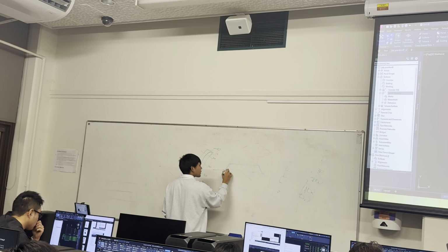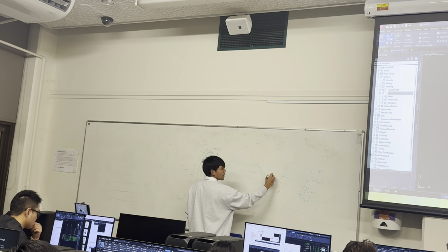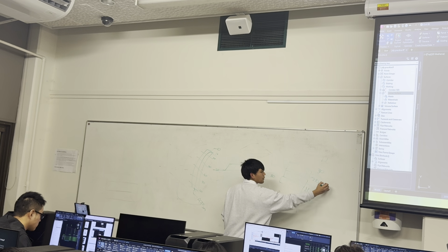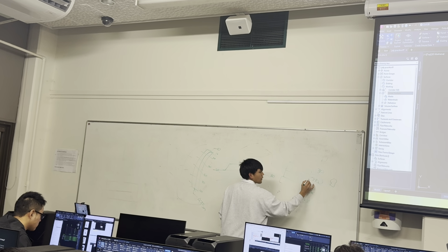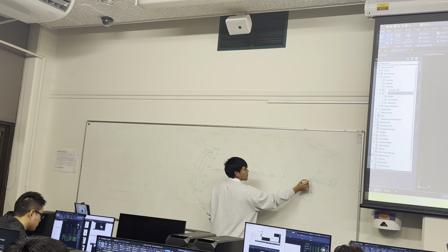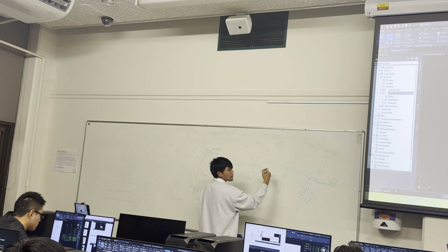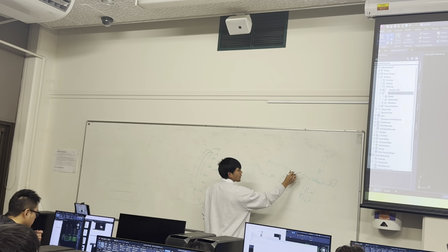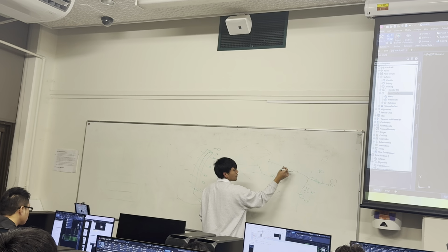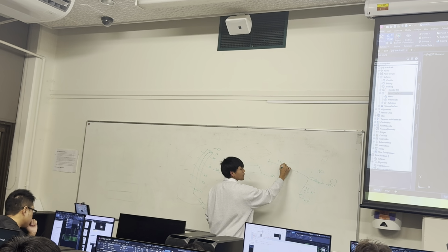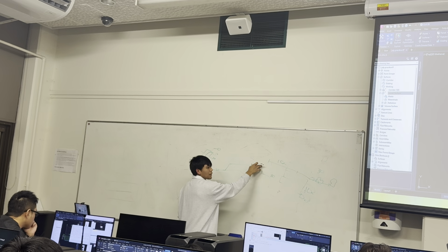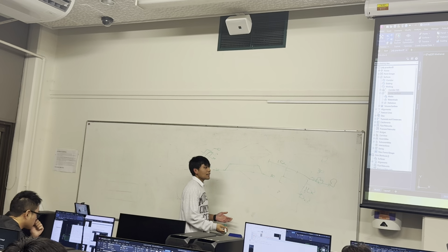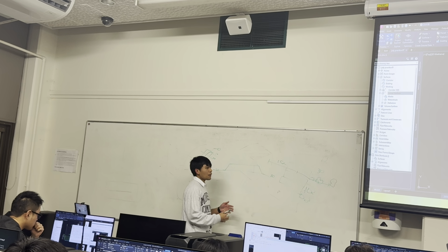We will have some distance, right? So for example, let's say this is the 20, so it's here, and we have, say, a tree here. For the purpose of this course, I only want you guys to do 15, either side, so 15 meters, 15 meters. Anything from the left side, 15 meters, anything on the right side, 15 meters, I want you guys to include. Anything past that, I don't want you guys to include.